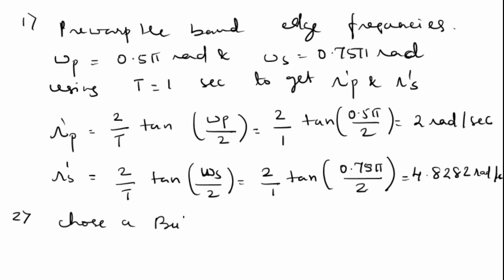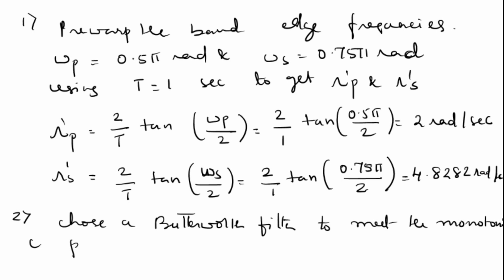Second step, choose a Butterworth filter to meet the monotonic pass band and stop band requirements.